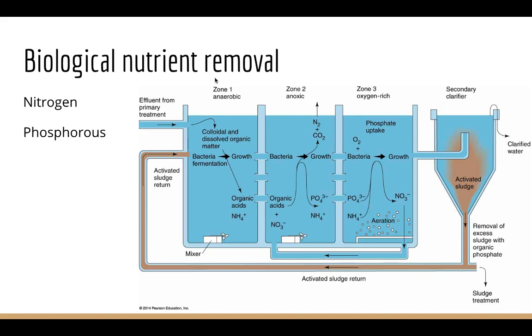So with the nitrogen cycle, bacteria are capable of doing this whole denitrification thing, where they can convert nitrogen back into nitrogen gas. The wastewater has ammonia in it, so what they need to do is convert this ammonia back into nitrogen gas, and then that nitrogen gas is just going to be absorbed by the atmosphere. Now, our atmosphere is mostly nitrogen, so it's not a huge deal for nitrogen gas to just enter the atmosphere.